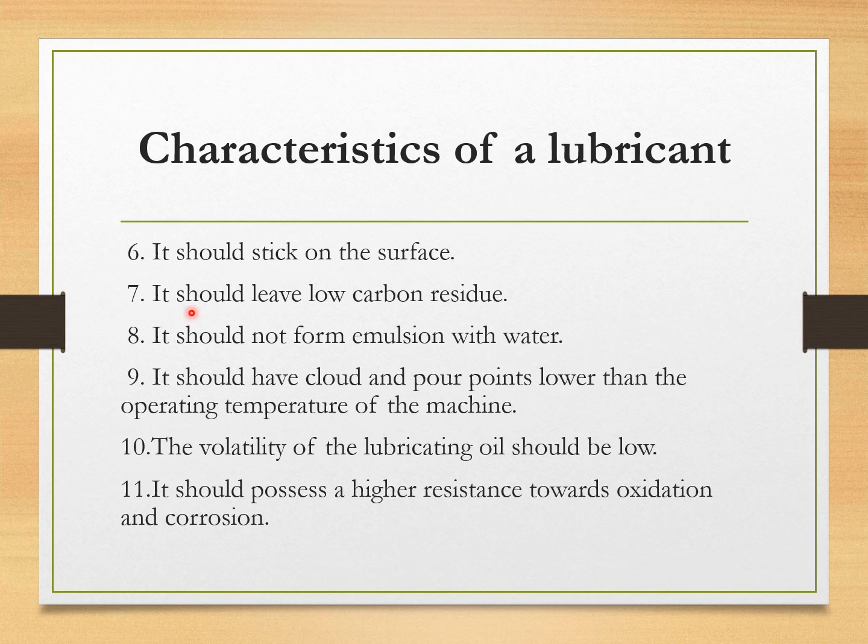It should leave low carbon residue. It should not produce any pollution. It should not form an emulsion with water. If it forms an emulsion with water, that is going to attract impurities or polluting particles. Due to that, friction increases.